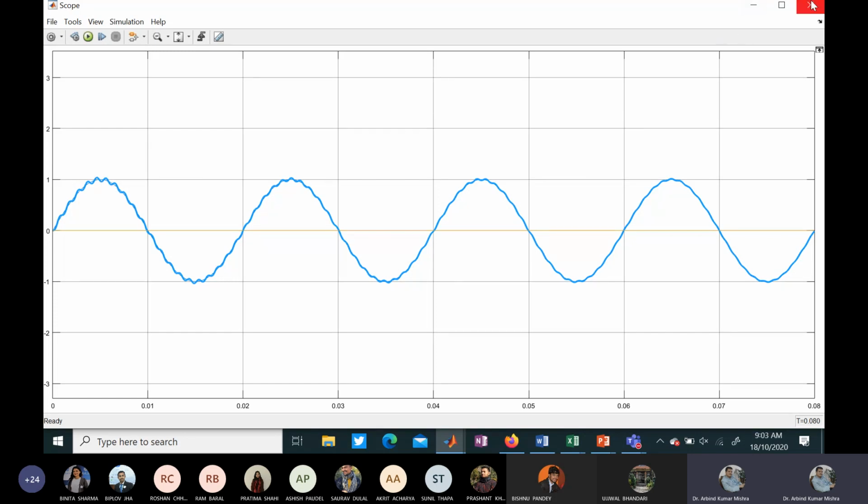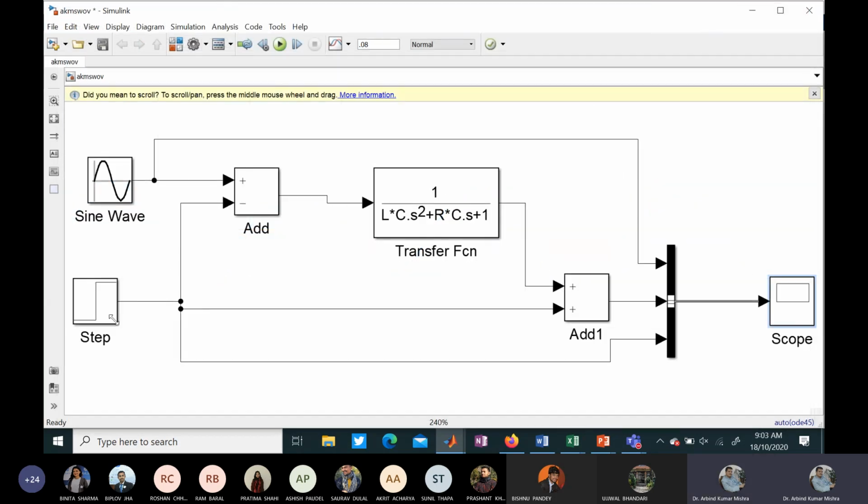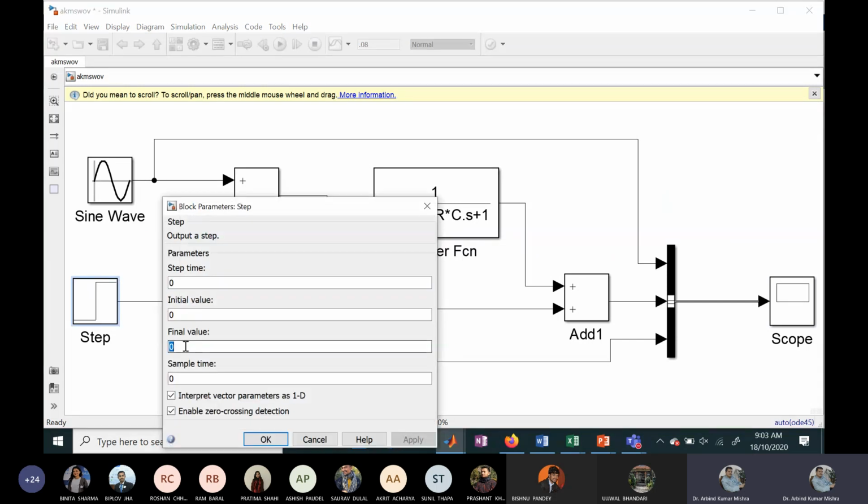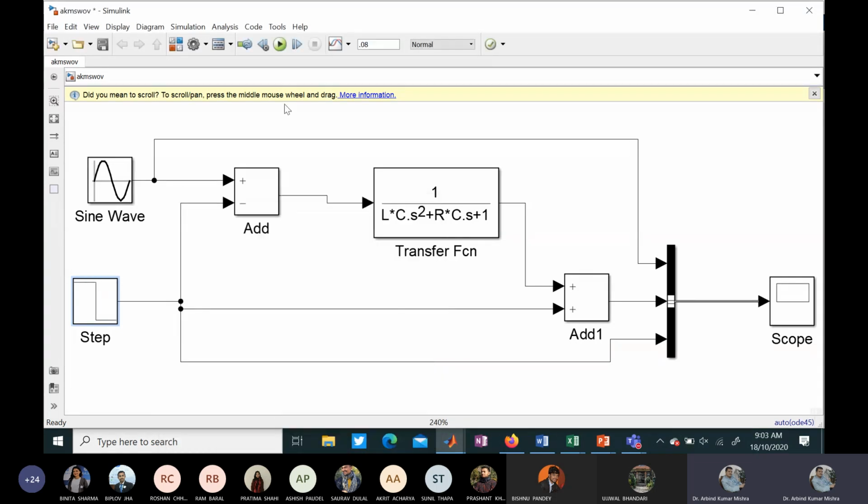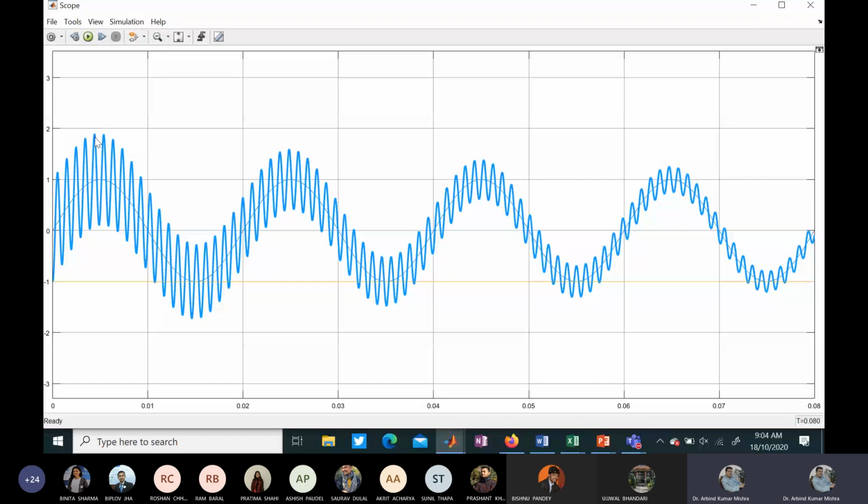so no over voltage. What will be the case if we consider a trap charge of -1, that is the opposite of the positive peak of the sinusoidal wave? If you run it, you will see that again it is 2 pu. So we have seen 3 cases, ranging from none to 2 pu.